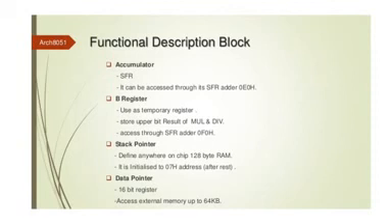Generally the data pointer is used only when we use external memory, because external memory has a 16-bit address size. Off-chip is nothing but external memory, so whenever we use external RAM or ROM, we use this.